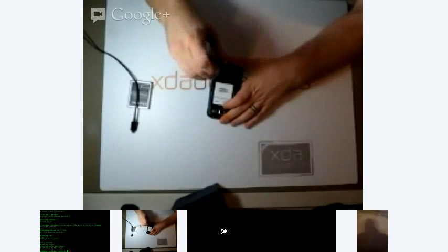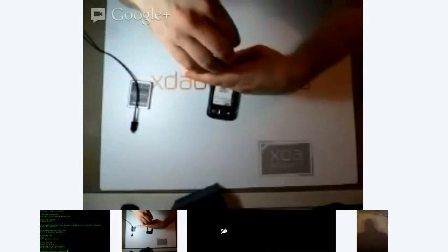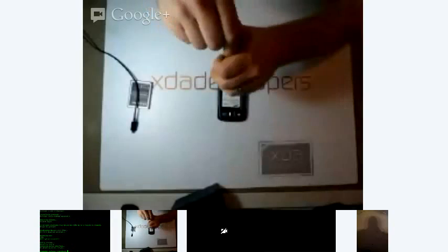So yeah, I didn't mention this. I mentioned this to some of you guys in the stream, but I didn't mention this to anyone on the YouTube video. I've got a project going on, the Open Galaxy bootloader, with XDA Elite recognized developer Rebellos, and also Elite recognized developer Rallic Dev. We're actually working on booting the Exynos 4412 processor using a version of U-Boot, which we're calling the Open Galaxy bootloader.